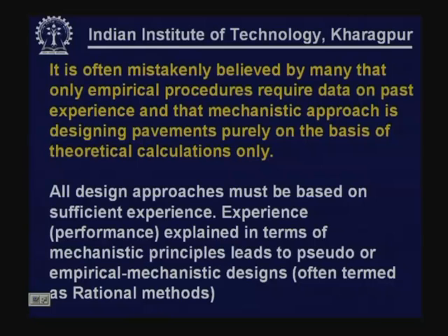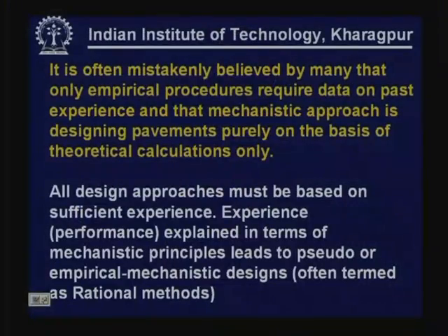It is often mistakenly believed by many that only empirical procedures require data on past experience, and that the mechanistic approach is designing pavements purely on some theoretical calculations, and then using some calculator or computer we are trying to design pavements. People often say, when you say I am going to use elastic theory, this theory, that theory, this is all purely theoretical, there is nothing correlated to practice. It is a mistake. Any design procedure has to be on the basis of observed performance. By the mechanistic approach, we are only trying to explain the performance in a more rational and more fundamental manner.